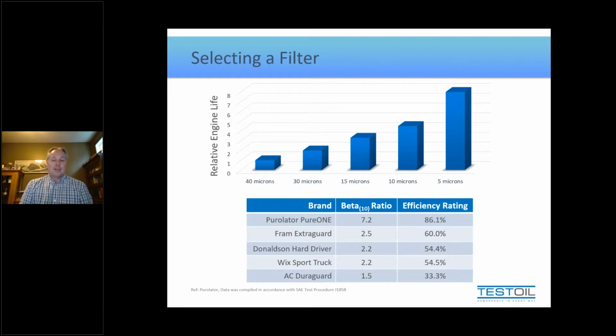So I was curious. Knowing the resources I have, I was able to look up who actually built the filter, and it was a company called Intertech. I looked at the specifications for the filter, and lo and behold, it was the same 10 micron absolute, 2 micron nominal that my OEM filter was. It just was a little bit pricier. They told me specifically not to buy the local, North American brand. They told me to buy the Japanese version, that the imports were better. So I looked at the import version, and it was the same answer.